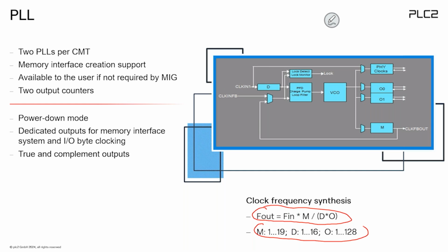The use case for the PLL is as a dedicated frequency generation component for memory interfaces generated and implemented in the FPGA. Especially today, DDR3 and DDR4 need very, very accurate, very high frequencies in order to operate correctly. And these elements, the PLLs, are used for this.